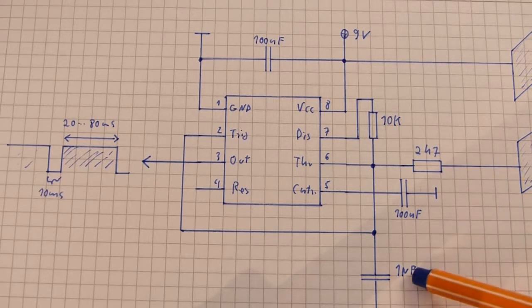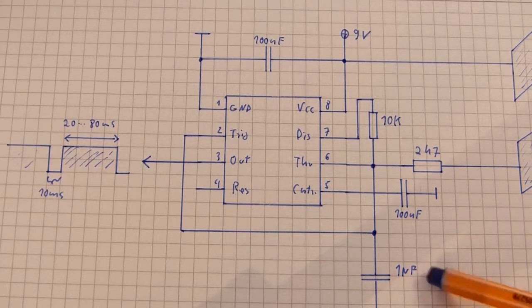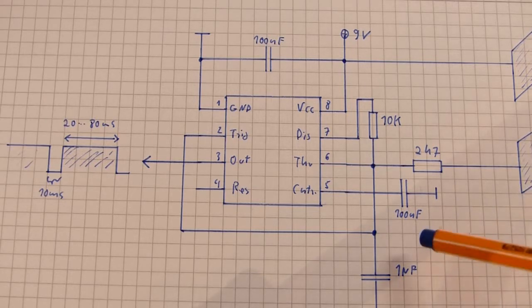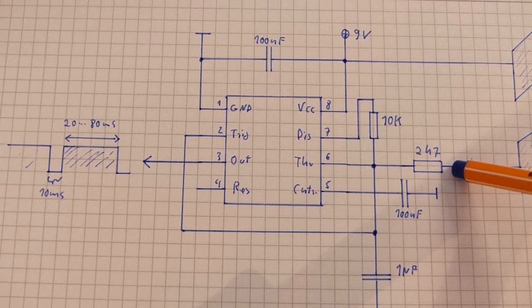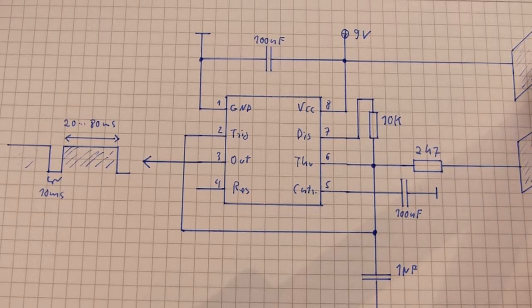And here's the capacitor, a 1 microfarad capacitor, the first factor that specifies the impulse length. And you can see that the resistor is replaced by this one here. This is just for safety purposes. And these two plates here have to be connected to your human skin. In my approach, these are small sheets of copper, which I'm fixing to my fingers by using duct tape.